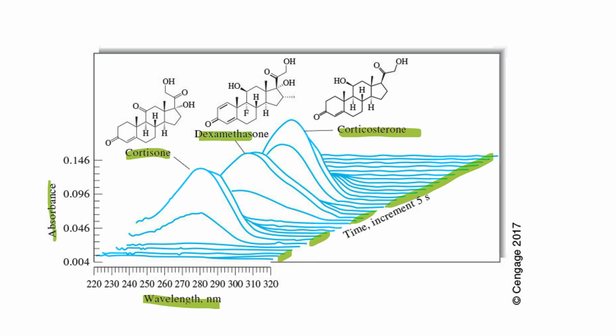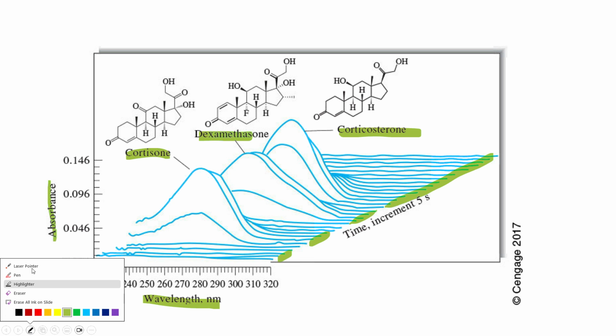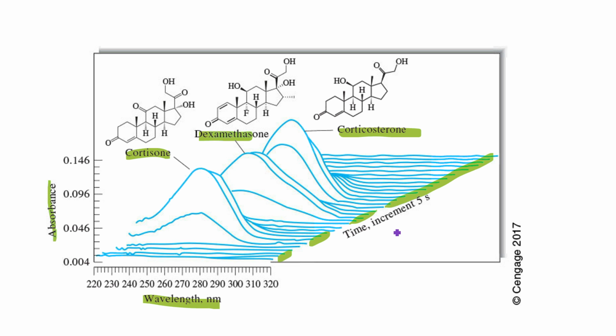And I'll tell you about today's standards. The spectra over 5 seconds is extremely slow. So most modern systems today will do 100 spectra per second in a high-speed system, and some will do 500. A few will do 1,000. But the thing you have to realize is the amount of data you're producing. So each one of these scans has got a certain inherent amount of data with it.